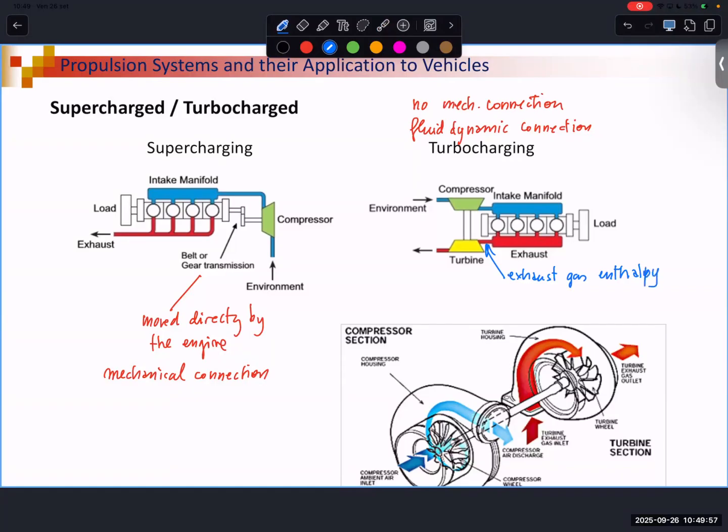to move that turbine. Let's consider, it's not exactly like this, but imagine that you are wasting the exhaust gas in the external environment. So you are wasting energy because you have a high temperature. So instead of wasting it in the external environment, you use it to move a turbine. It's not exactly like that because this is producing a back pressure. So the pressure here is increasing if you have the turbine. It is like you are getting some work at no cost. It's not exactly like this, but we can think really simple in this way.